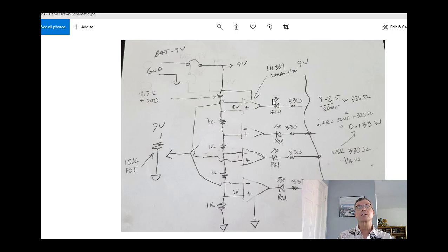So if the transistor is saturated, of course, it can eat quite a bit of current going down toward ground and with a low output voltage. So we say it can sink current. But if I now turn this transistor off, then I can't supply current because that NPN transistor won't supply current. So the take-home message is that your LM339 can sink current, but it can't source it.